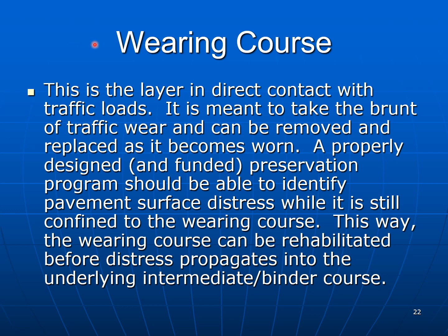Look at the wearing course. This is the layer in direct contact with traffic loads. It is meant to take the brunt of traffic wear and can be removed and replaced as it becomes worn.